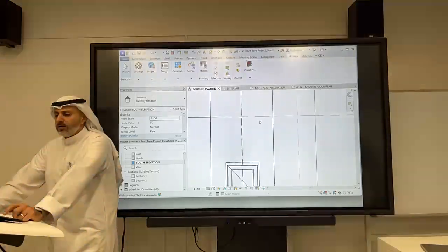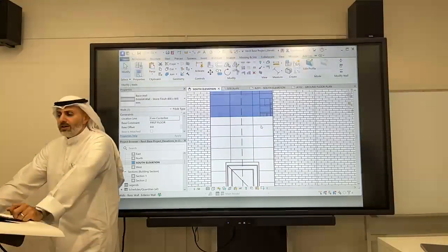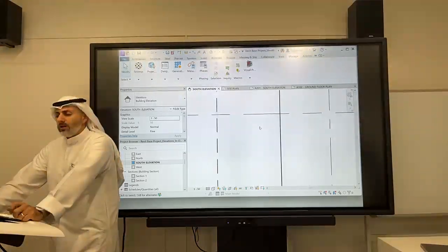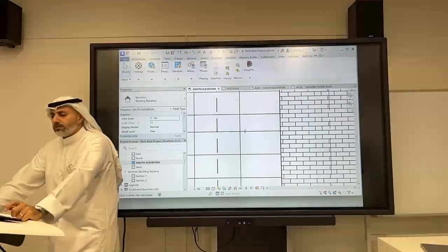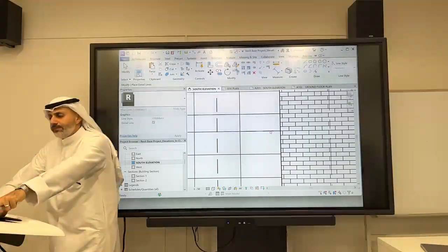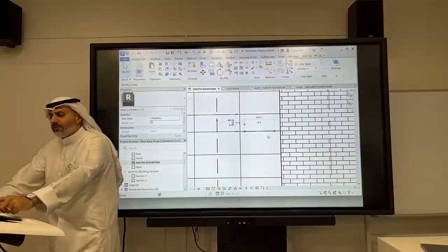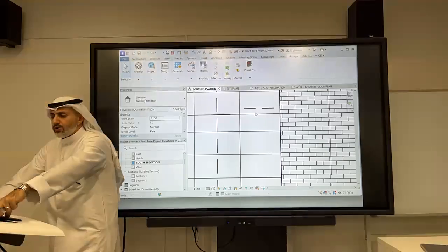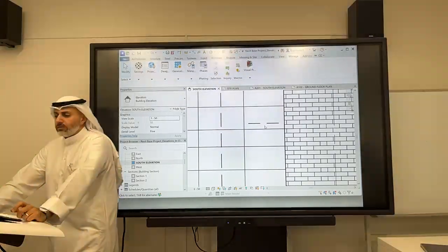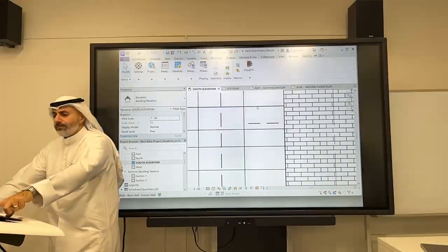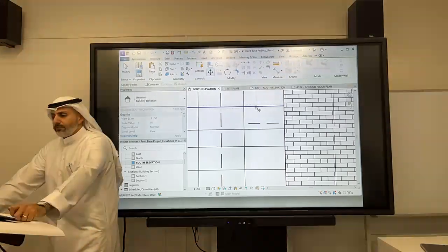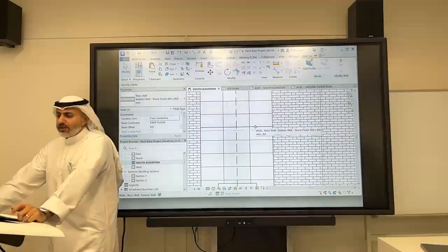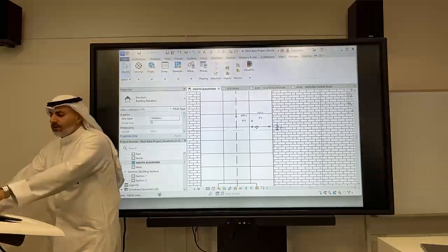It's the top of the wall. This is one wall. This is another wall. Right? There's a gap beneath. The material doesn't continue. So you need to also manually do that. Create a line beneath. Move it to the tile height. Let's say 400 for example is mine. So now I know that this line should be here. So then tab. And make sure to delete all your detail lines.